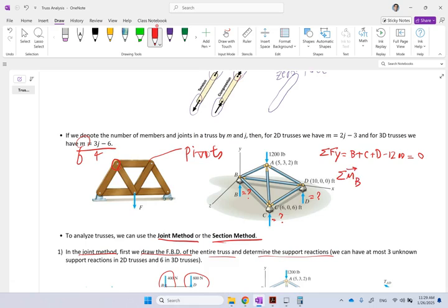You cannot go clockwise or counterclockwise because it's 3D, so you have to use the general formula for moment, which is arm vector cross the force vector. So in this case, for this force 1200, if I want to calculate the moment, I need to have this vector here, right? This R vector, whatever you want to call it, R of A slash B. So that force should be crossed with 1200.